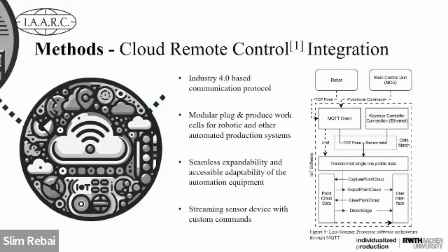The other way around, we are getting constant state data of where the tool center point is in terms of transformation, as well as the speed of the current TCP and things like that. So currently we are sending this state to the local MQTT broker. We can say that this robot is now an IoT-enabled device that is standalone, existing in the workcell environment by itself. Additionally, the laser profiler.